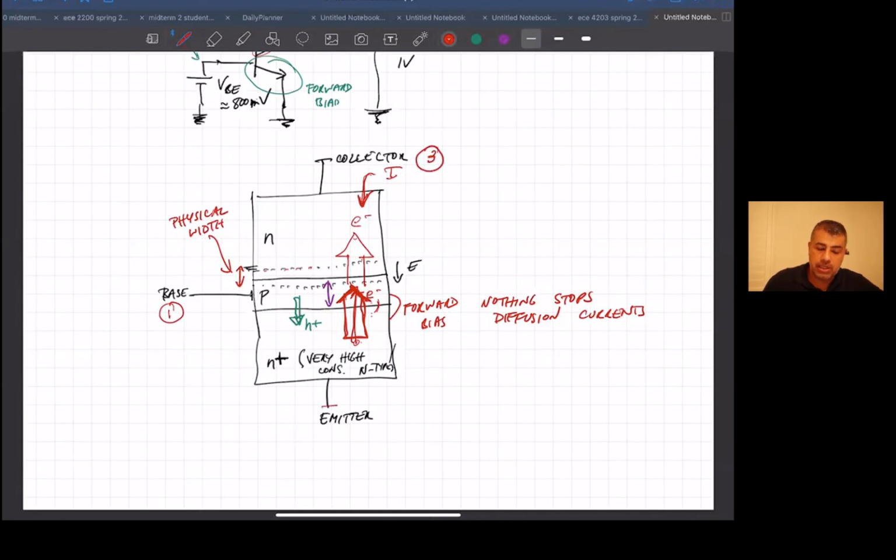Okay, with this guy being the common voltage. Because this PN junction here is forward biased, we get a diffusion current going from the emitter to the base, and then if the base is narrow enough, it gets collected by the collector and appears like this electron current. And basically the base-emitter voltage is controlling that current. Okay, so that gives us our voltage controlled.